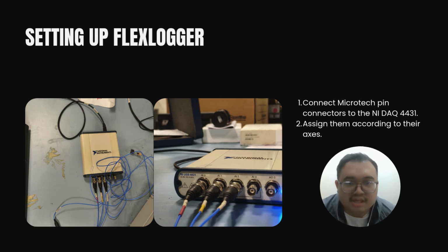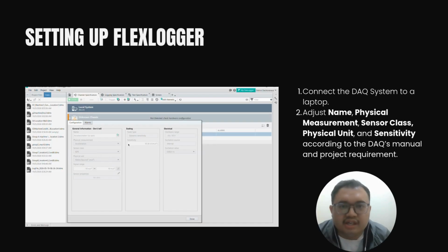Once the sensors in the motor shaft assembly are set up, it is now time to connect the microtech pin connectors to the NI data acquisition 4431. We must assign them according to the axis, which is X, Y, and Z. After that, connect the DAQ system to the laptop.